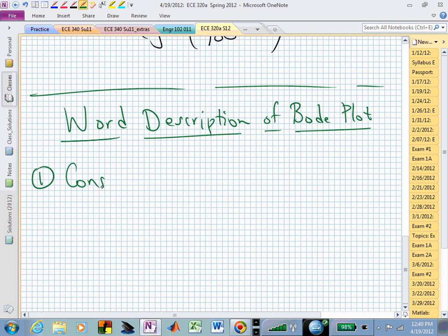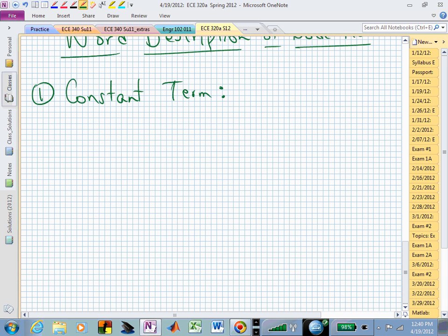The reason I'm able to do that is because we're talking about the magnitude in dB and the phase in degrees. Once I've put each of these individual parts onto my graph paper, I can sum immediately all the contributions from each term because of the dB fact of the magnitude and the angle of the phase relationship. Those are all additive type operations.